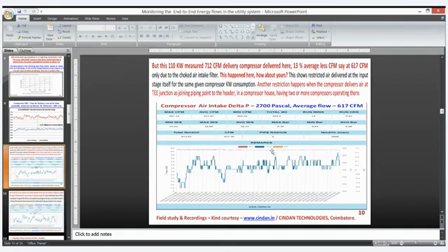When it is supposed to deliver the 100% flow, this is not able to deliver because the input is getting choked. So that is why I said, let us monitor the end-to-end energy loss in the system, not only on the plant, end-to-end of the utility, end-to-end for each and every element: the compressor at the input, the compressor at the post air cooler, the compressed air pressure at the refrigeration dryer, and what is given to the process.